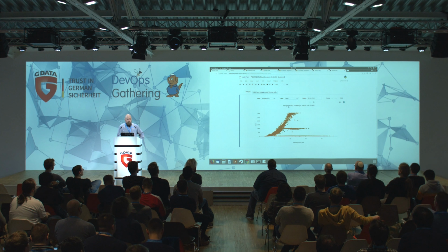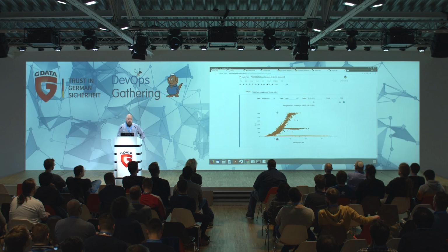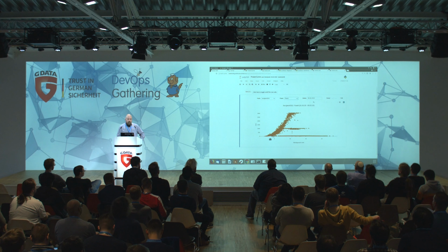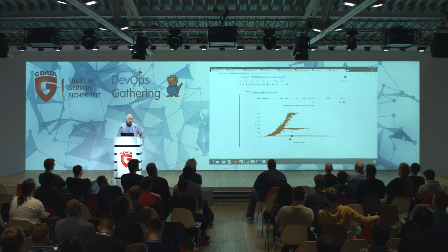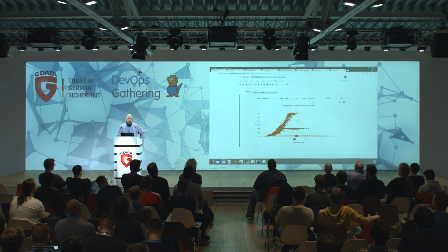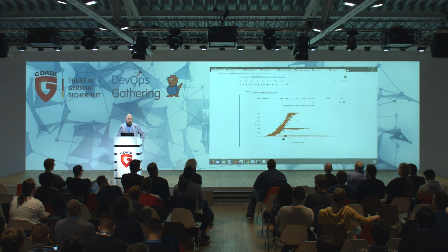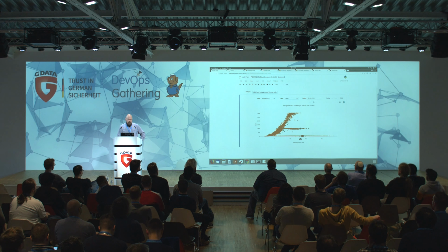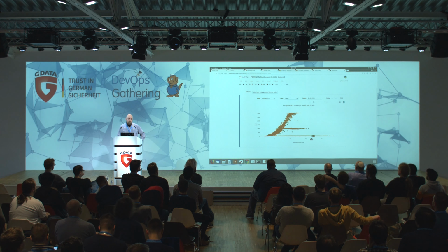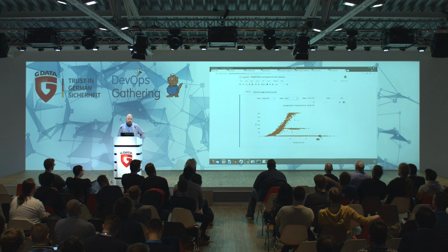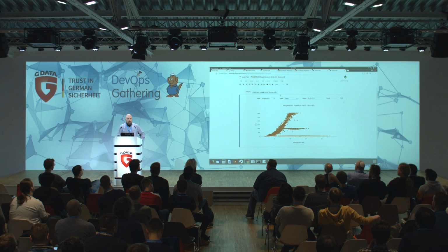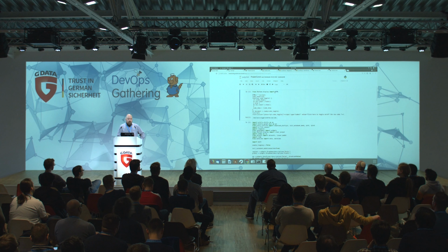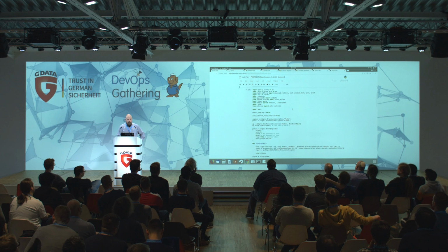It's a 2-dimensional graph. On the y-axis you can see the power, and on the x-axis you can see the wind speed. And this line is when the wind turbine is power capped, so it can only produce 1 megawatt regarding the wind speed. And here, with these high wind speeds, the power is 0 because in a storm it will turn off automatically.